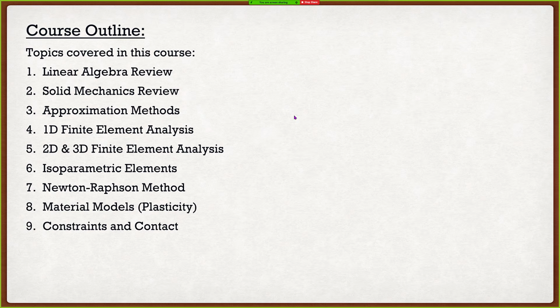We have the mortar, we have the grout, we have the steel, we have the block. So what we're going to have to do is talk about how we can connect these things in the finite element program. Now again, topic number 9 here, this is going to be more Abaqus based. I'm going to show you how we do this in Abaqus. If you are doing, let's say, a steel beam and you have some bolts, I'm going to show you how to put the bolts into your model, stuff like that. So you should be good to go.